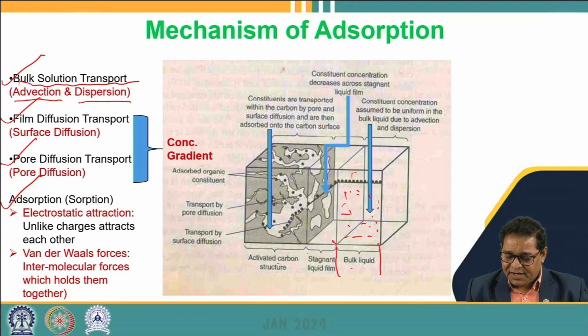So in this diagram we divide different phases. Presume this is the liquid phase where the pollutant is dissolved at a uniform concentration in the bulk liquid, and immediately next to this there is a stagnant liquid attached to the adsorbent. This is the interface of the adsorbent where a stagnant film appears on the surface, and the transport of molecules...